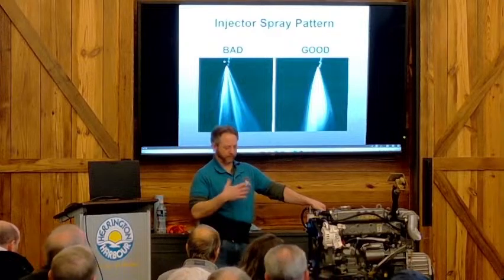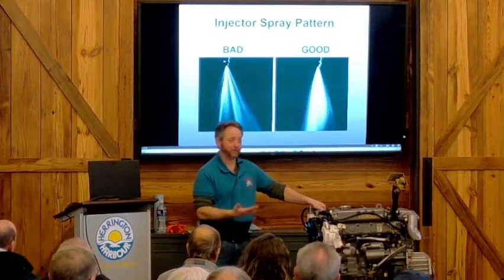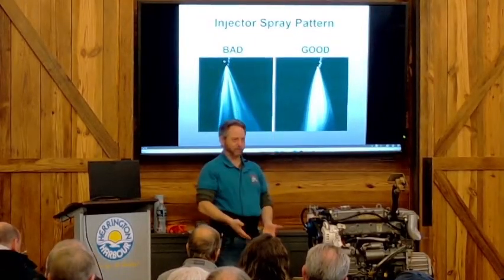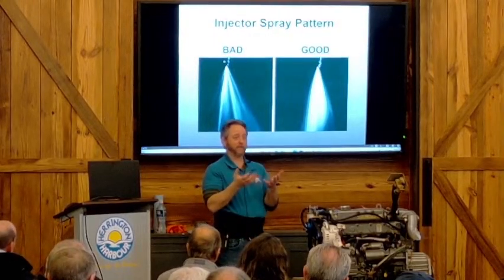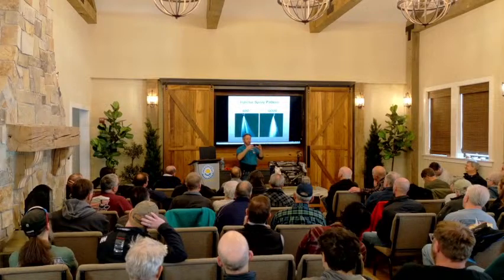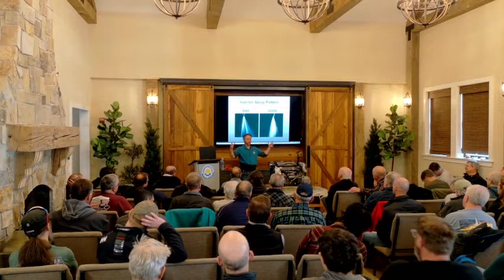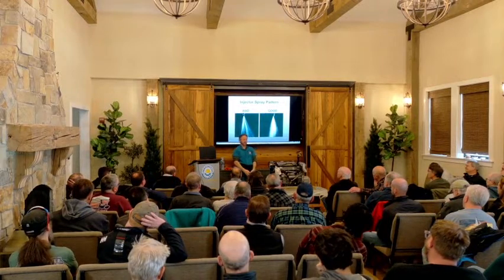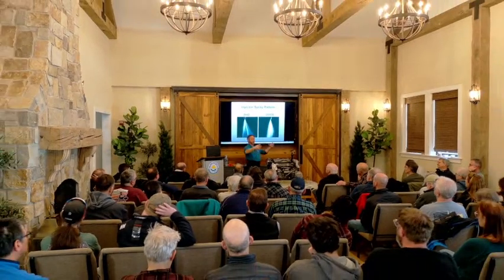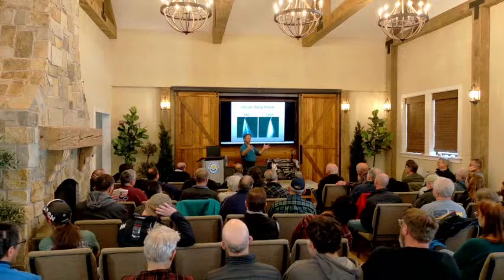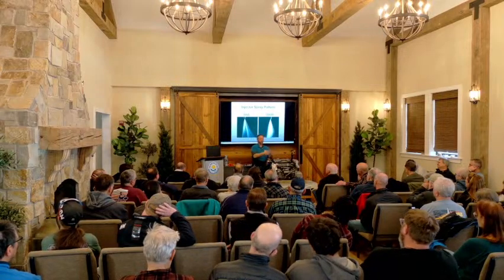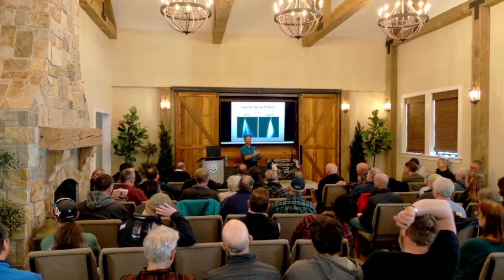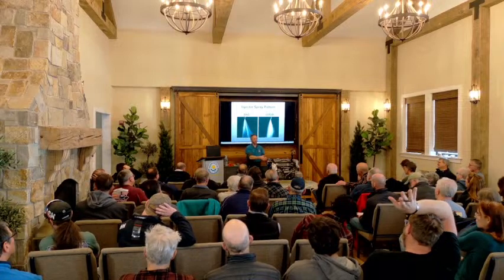Okay, so let's go back to science class in high school or middle school. We know hot air rises, cold air sinks. Hot air rises because it's lighter, because the molecules, when they're heated up, get further apart. Cold air sinks because the molecules are closer together and it's heavier. So when you have a hot engine room, the molecules are further apart, so not as many oxygen molecules are getting pulled into the cylinder. That's why it runs rich and produces black smoke with a hot compartment.